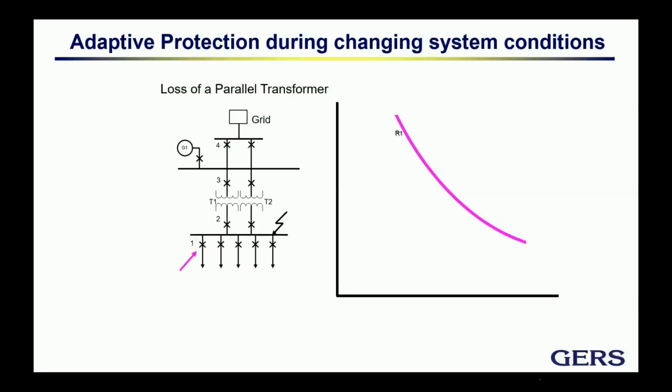Then you calculate the fault current by using a software, and with that software you determine that the short circuit current is IF. This is the fault current, and for that typical curve, the time of operation for that relay will be T1. Good enough. Now we will determine the setting for relay 2.